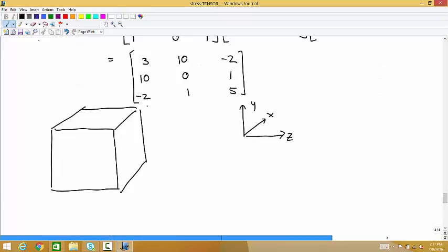So on the z face, we have 5 as the normal stress. In the positive y direction, we have 1. In the positive x direction, we have negative 2, so in the negative x direction, we have 2. That means that has to match, and that has to match.